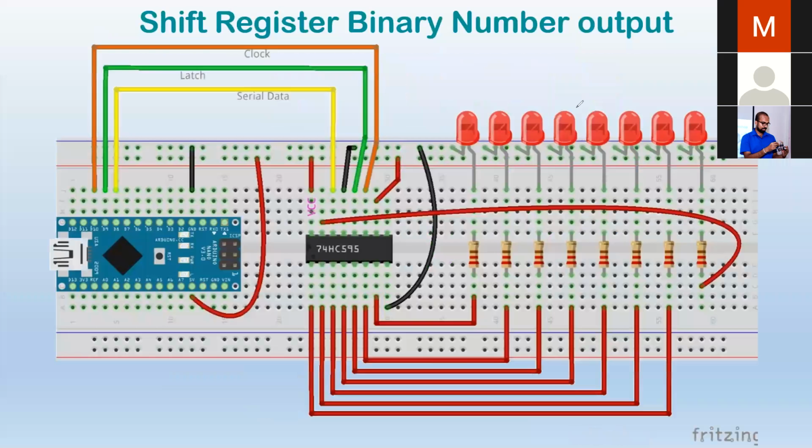Usually if you are going to control, here we have 8 LEDs, right? You are going to need 8 pins, right? So in the Arduino, you are going to use 8 pins, and that is something you cannot do in some cases. Imagine you have to make a really big LED design circuit, and you have to use like 1000 LEDs. Obviously, even if you use the biggest Arduino, like the Arduino Due or the Mega, you don't have 1000 pins, right? You don't even have 100 pins.